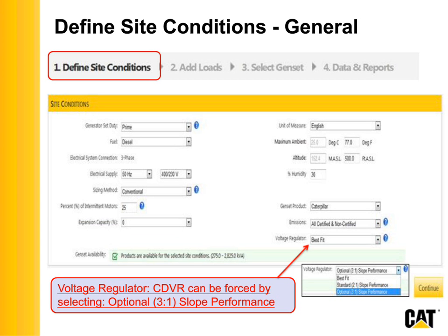And we load both sets of transient response data into SpecSizer. The tool, set on best fit, will automatically compare both sets of transient response data and select the smallest genset for you, the smallest ekW kVA rating.